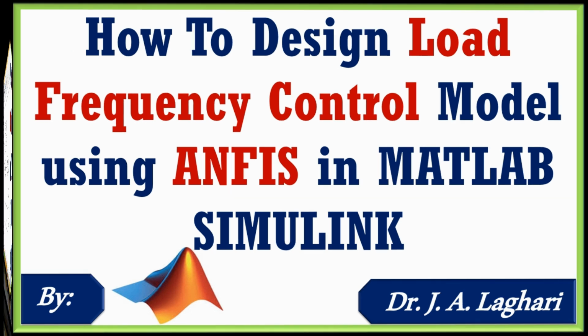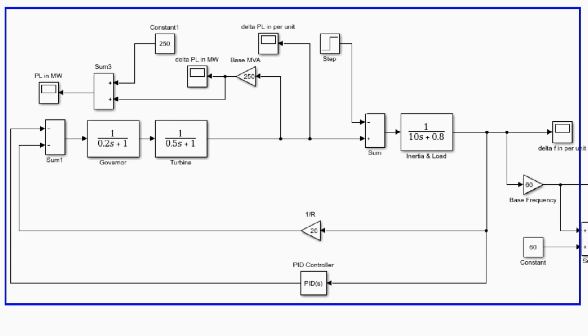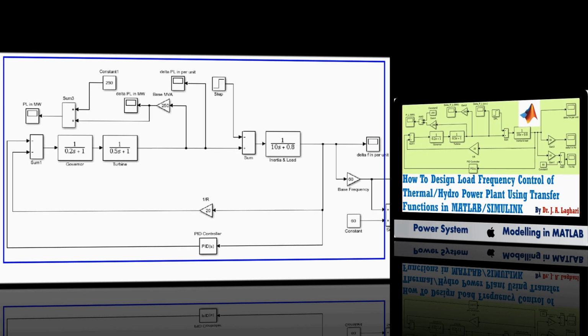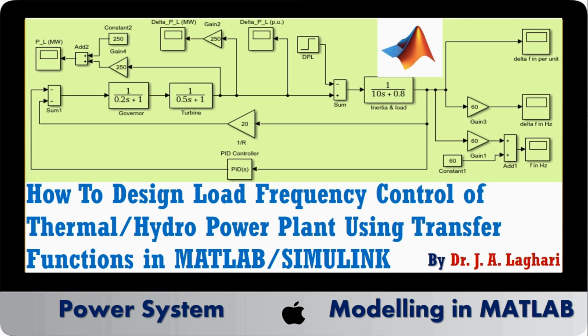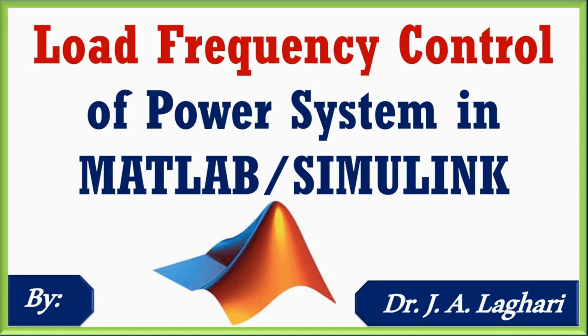For your convenience, I am considering this simple load frequency control model of the power system as shown here. On this topic, I have already made the video, namely how to design load frequency control of thermal or hydro power plant using transfer functions in MATLAB Simulink software. Therefore, if you watch this video and apply the ANFIS controller in this model, then this model can be used for your master degree research or one of the PhD research objectives.